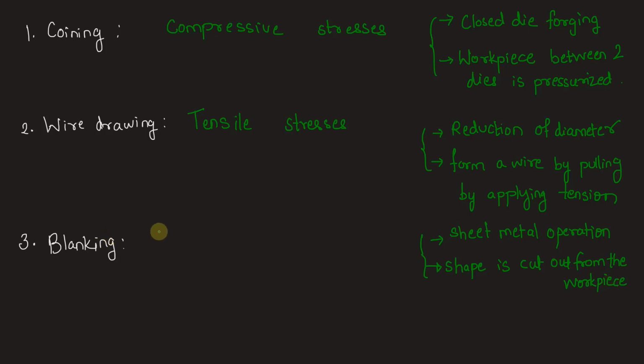So we can see that shear stress is developed at the interface where the workpiece and the material removal mechanism works. There are various types of machining processes used to carry out blanking. Punching is the process used. So by punching the shape in, we thereby create shear stresses on the interface, and those shear stresses should be higher than the shear strength of the material of the workpiece so that the cut will happen.